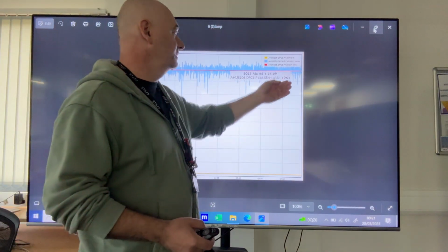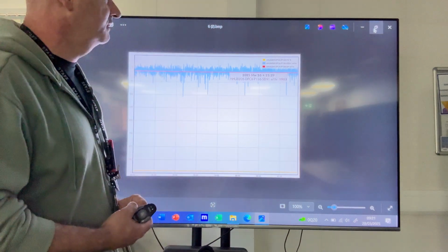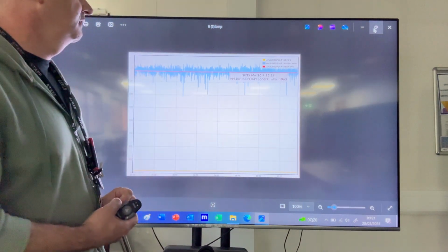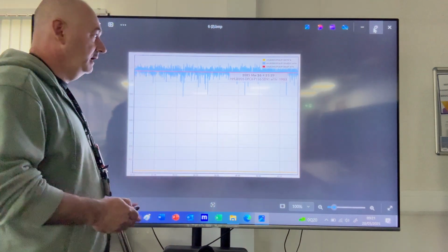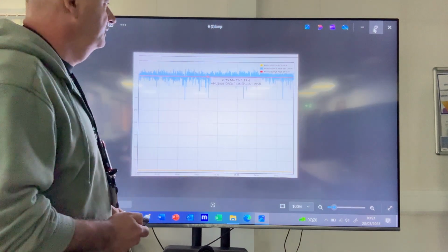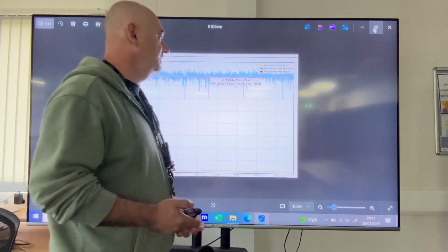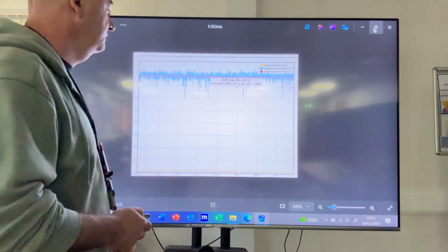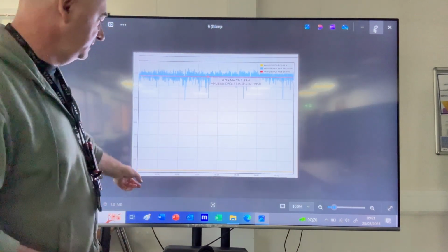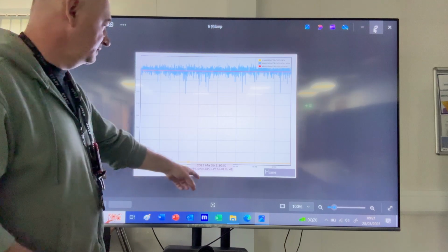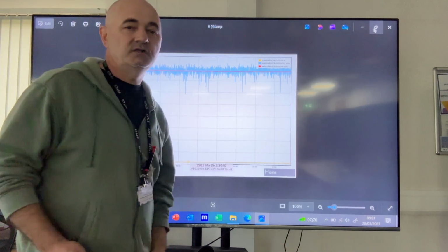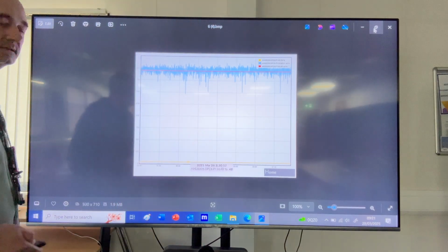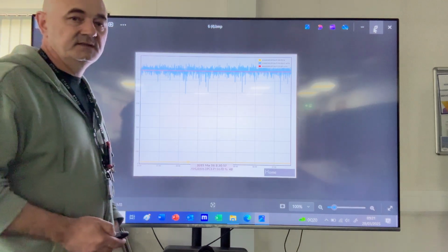To see it clearer, you see here I put a date like 2025 March 26 at 4:25:29. The sensor shows me this value, 1963 meter cubes per hour. I want to see the set point. The set point is 1950, which is alright, it's almost similar, we have this variation. And also I want to see the damper, it's 42%, it hasn't been changed for a long time. This is the beauty of this system.